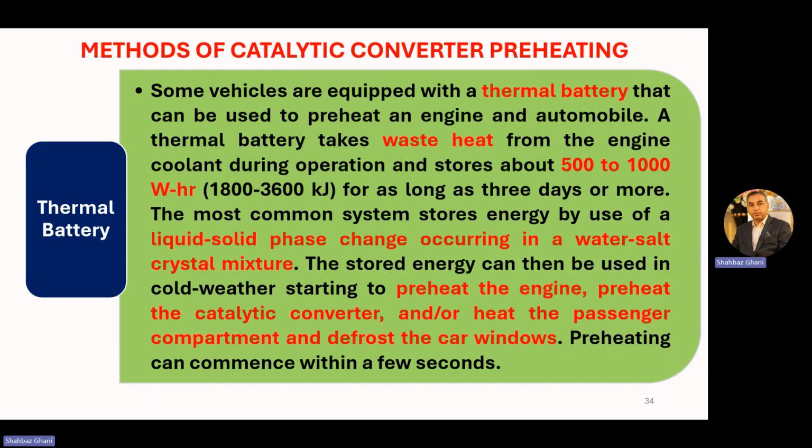Now, the other method is thermal batteries. Some vehicles are equipped with thermal batteries that can be used to preheat an engine, an automobile. A thermal battery takes waste heat from the engine coolant during operation and stores about 500 to 1000 watt hours, meaning 1800 to 3600 kilojoules, for as long as 3 days or more.